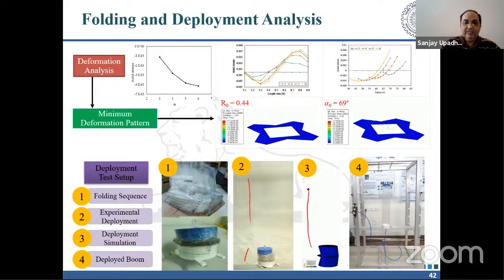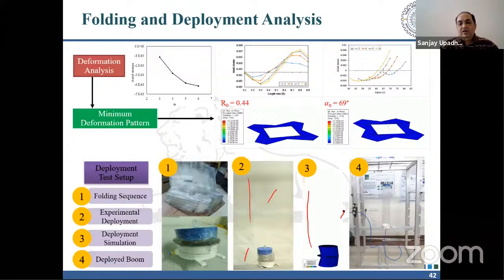It will be inflated. Experimentally and analytically, we have compared our results: folding sequence, how to fold it, experimental deployment, deployment simulation. We have considered first the boom, deployment of the boom. If you are talking about the inflatable strut, first we have considered it as a boom. So the boom, how to fold it, we have studied this.